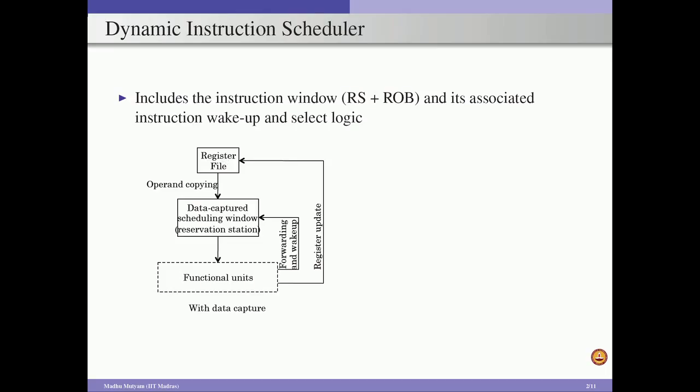And this register file consists of both the rename register file as well as the architectural register file. So, of course, we are updating the value only to the rename register file. As a result, with this type of design, whenever we are dispatching an instruction to the reservation station, at the time of dispatch, we read the values from the register file if the values are available.